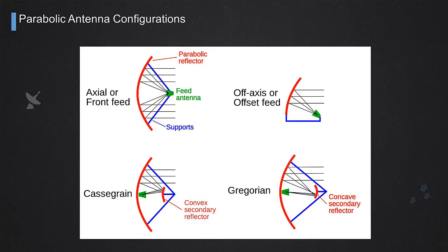The feed is put on the main reflector in the focal plane of the reflector, but the rays are not hitting the feed directly, they could not, because it would not be in the focus. Rather they are reflected by a secondary reflector of convex shape, and this one is now concentrating the rays towards the feed. So it's a double reflector configuration.